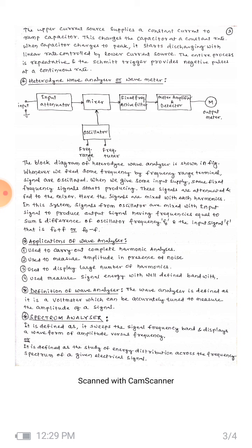200, 1000 and 3000 hertz. The various applications of wave analyzers are: it is used in electronic equipment, in sound measurements, and in vibration measurements. It is used in industries to check sound and vibrations generated by rotating electrical machines and apparatus, so that they can be reduced or eliminated. It is also used to measure amplitude in the presence of noise.